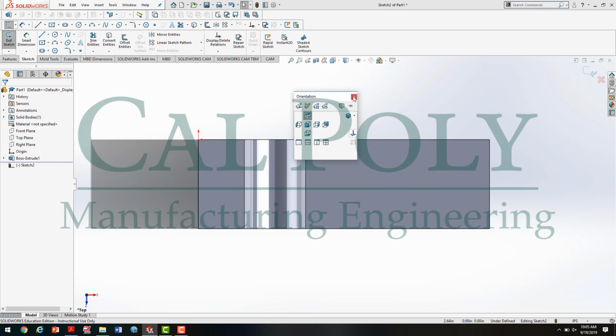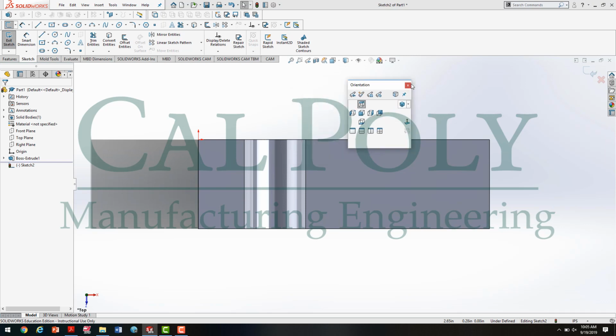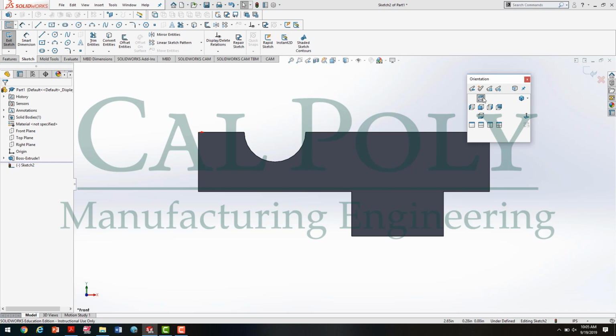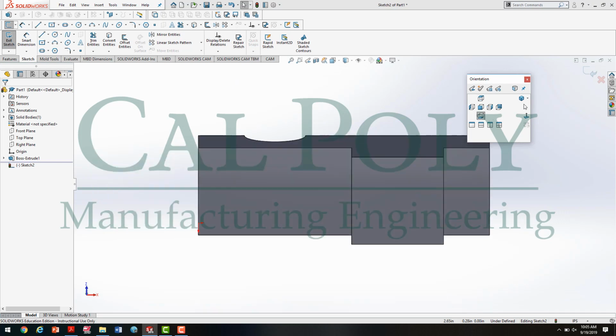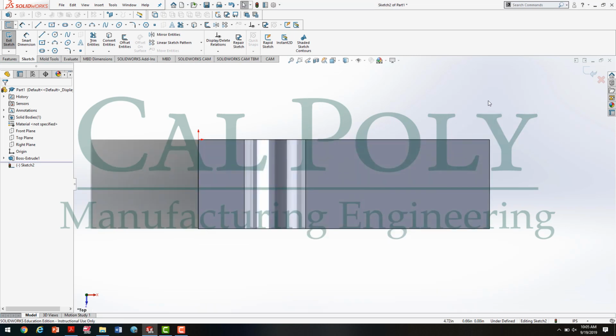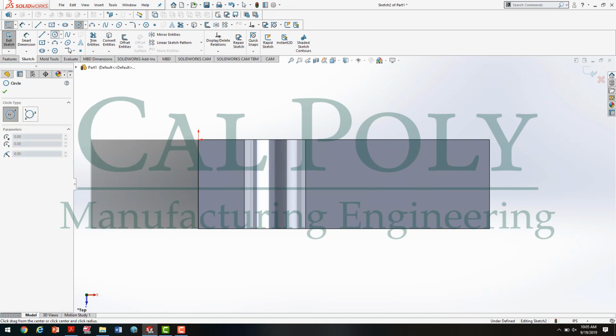or hotkeys. Now if you wanted this menu to stay up for orientation, notice there's a little pin right here. If I pin it and I start clicking on other views, the view box or the orientation box stays active. I'm not a big fan of keeping things pinned to my window, so I'm going to unpin it and click back on top view. Now, we're going to create two circles, and we're going to define their size and location with respect to the part model we just created.